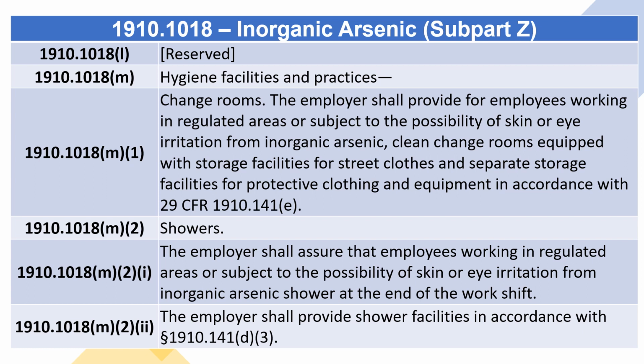1910.1018(m)(1), change rooms. The employer shall provide for employees working in regulated areas or subject to the possibility of skin or eye irritation from inorganic arsenic, clean change rooms equipped with storage facilities for street clothes and separate storage facilities for protective clothing and equipment in accordance with 29 CFR 1910.141(e).